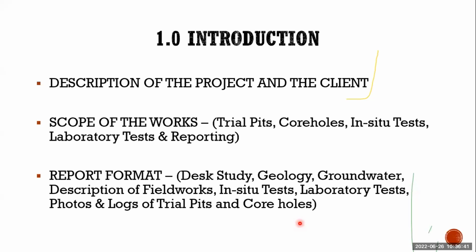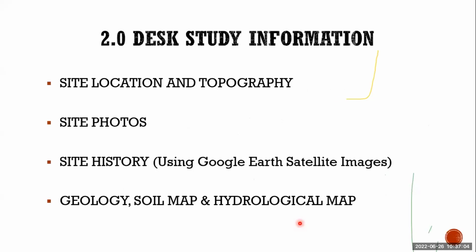And you can mention the report format: desk study, geology, groundwater, just an outline, description of field works, in-situ and laboratory tests, photos and logs of trial pits and core holes, and interpretation of the data. Next slide.